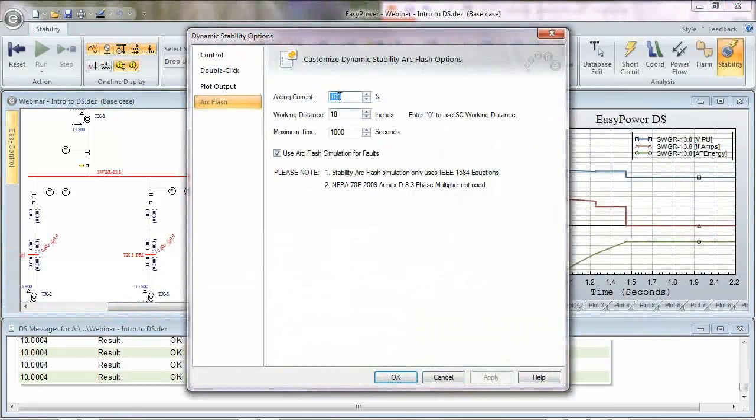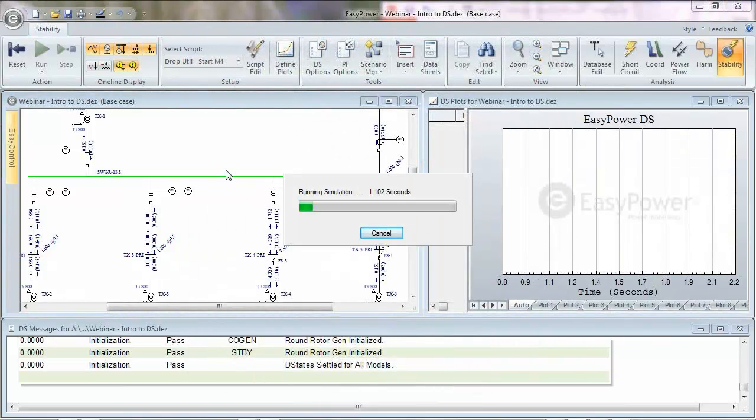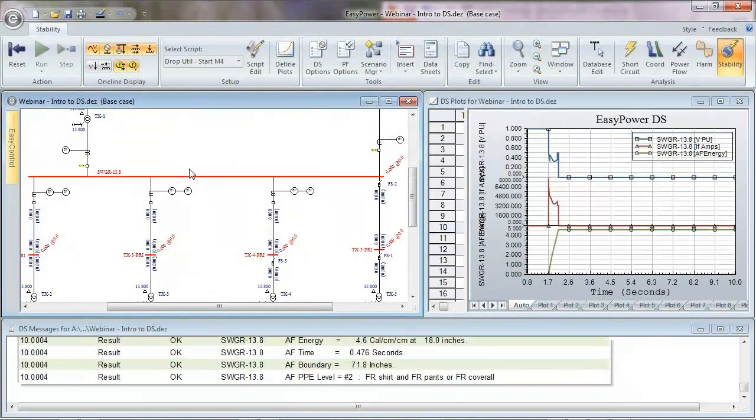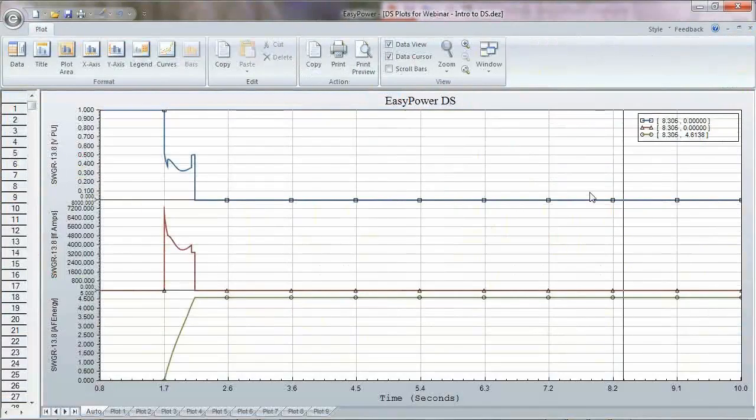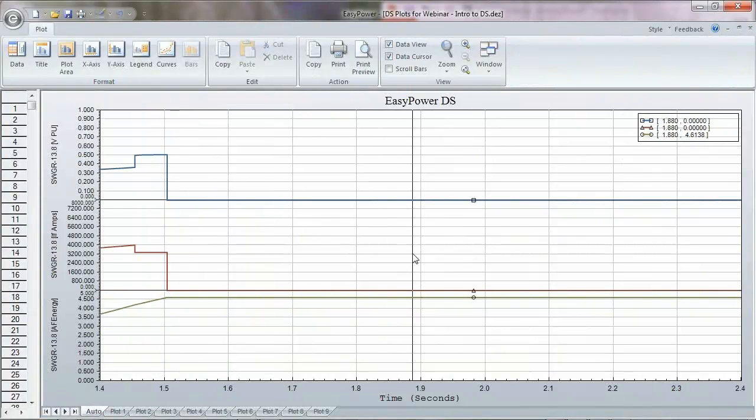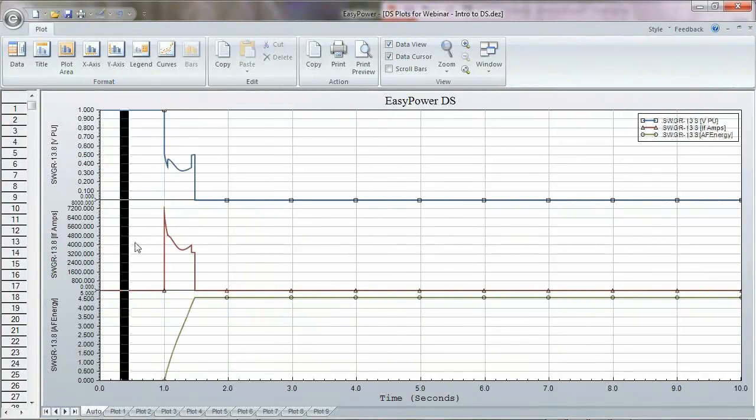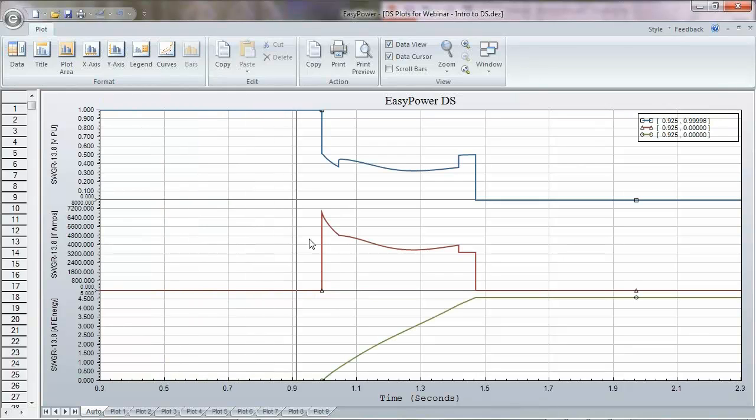What would happen if we were to change this to 85%? Wow, significantly different result. Different tripping time. Oh, let me do that again. Completely different behavior. Much different due to, you can actually see the AVR response in here. Look at that. You can see the AVR affecting fault current. And then it trips only briefly and then goes off.